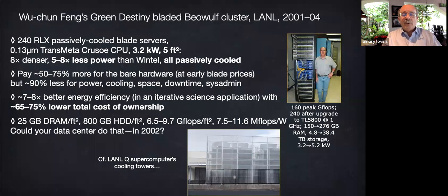Well, at 1.6 volts, a 0.5 gigahertz Pentium 3M compared with the Transmeta TM5600, 600 megahertz that you saw earlier, that means 122°C versus 64°C, almost a factor 2 difference in chip temperature. That implies a 60 times longer hardware mean time between failures for the efficient cool blade server. So as Dr. Feng said, less power, less heat, passive cooling, and greater reliability meant his cluster computer needs better than faster and more demanding machines.